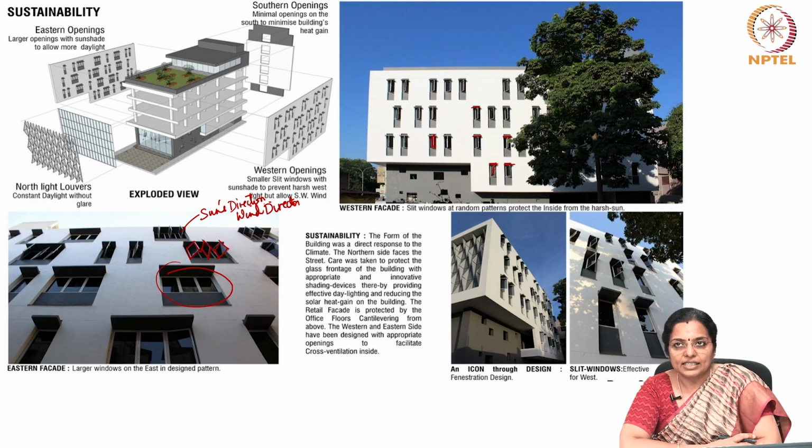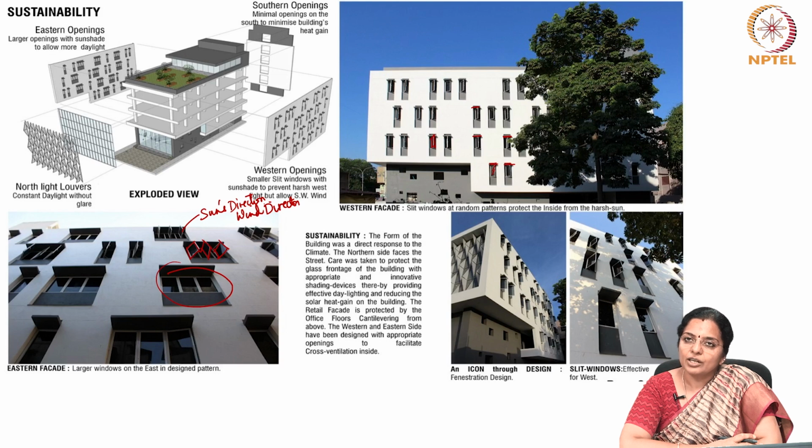On the western side, in Chennai during summers, the setting sun moves northward. During such months, the fins provide diffused light. During other times, they cut the glare from the bright sky. It also offers an interesting view of the street from the office spaces, breaking the monotony of the spaces. Also, the glass used is solar rated glass to cut heat gain.